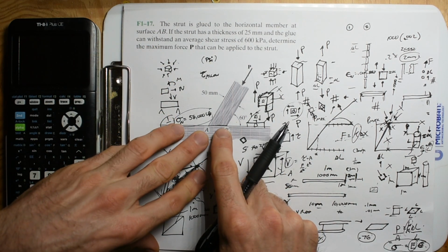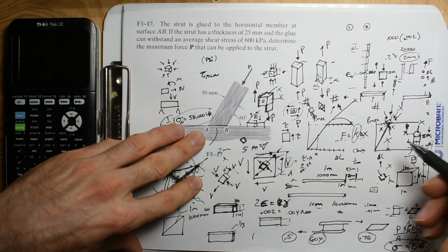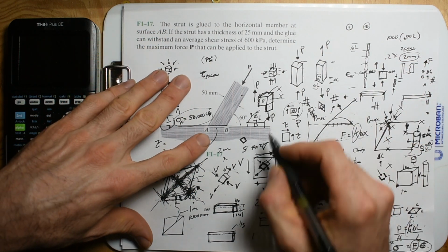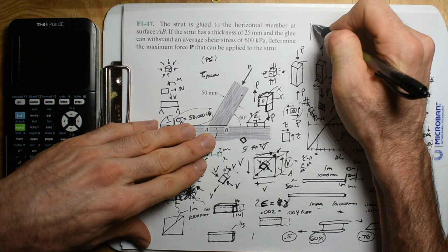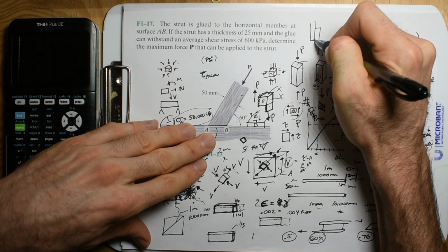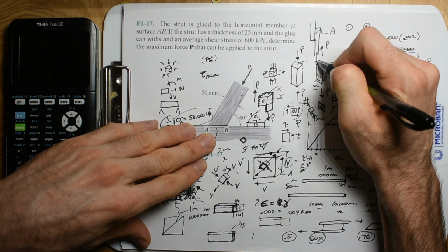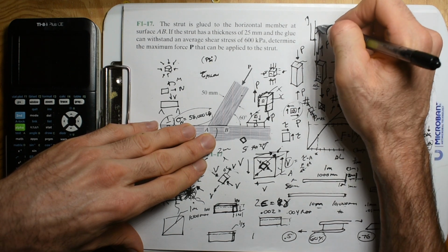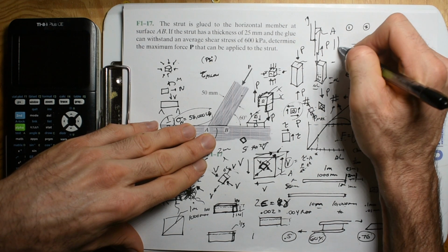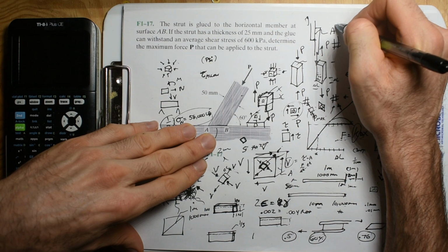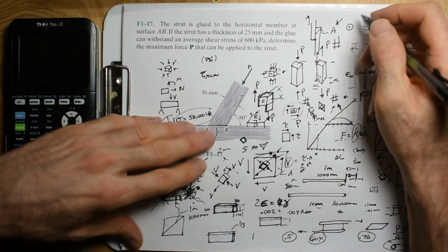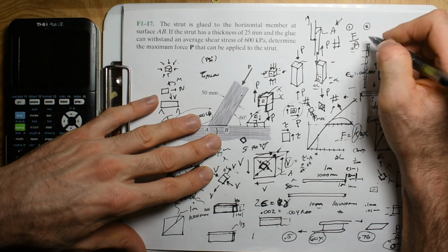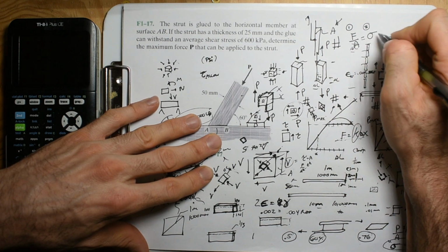But even just for myself, I have to keep saying that these relationships are empirical. You know what I mean? You put two glued joints together with a known surface area, with a known force, and put it in a device and pull on it, and guess what? You're going to get the max load, and then you know your area. So that's going to give you that PSI, that pressure. That's going to give you the force divided by the area, and that's going to give you the stress.